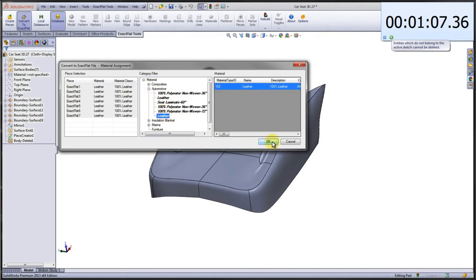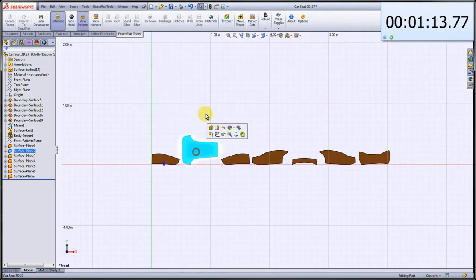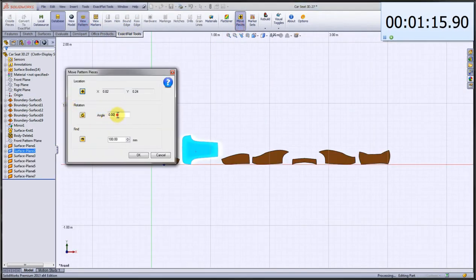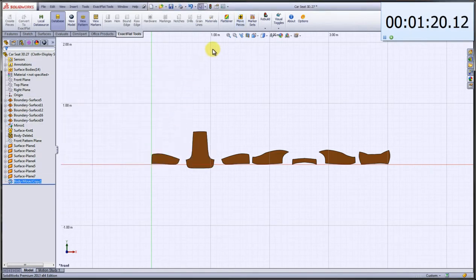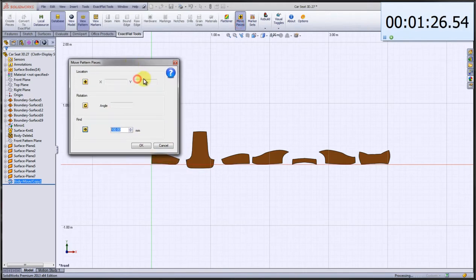What's going to happen now is the surface bodies are going to be indexed so that the adjacent pattern pieces will line up, and we're assigning material properties to the pattern pieces, such as Poisson ratio and Young's modulus, for flattening. What I'm showing right now is just laying out these pieces into a visual sewing layout.